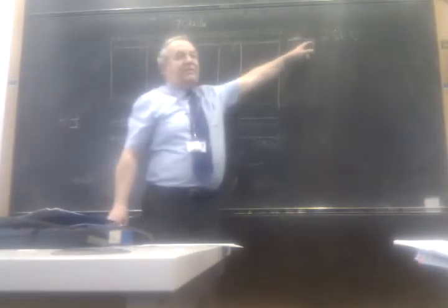Okay, so probably it said just determine the minimum design compressive strength of these walls. So actually the way you do it is in symbols, what I've just done before. We had a load of 70 kilonewtons per metre on there. So the first thing you've got to do is for each of the walls decide how much of that 25 kilonewtons goes into them. Before, we looked at three walls side by side and we shared the load in proportion to their stiffness. We do exactly the same here.